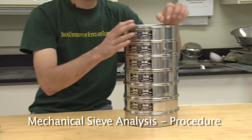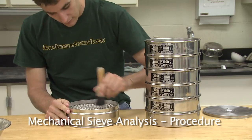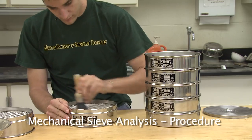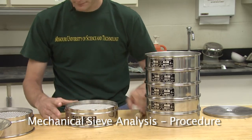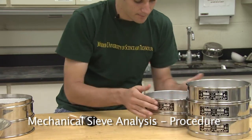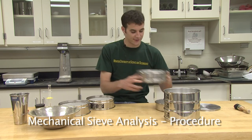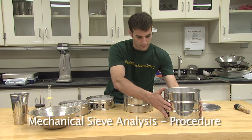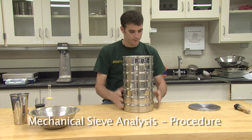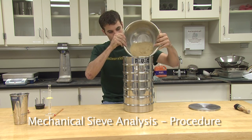Disassemble the stack of sieves and brush out the wedged particles in the screens. Do not use the sieve brush on the number 200 sieve, for this could damage the screen. Reassemble the stack with the smallest sieve on the bottom, in this case the number 200. Pour the soil sample into the top of the sieves.